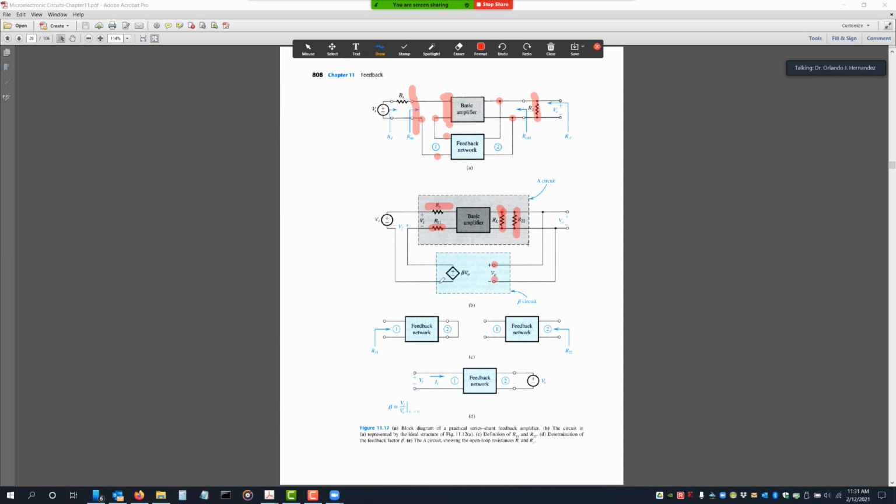So this voltage output over here becomes beta times this voltage over here, VO. And this can be applied to an actual simple negative gain op-amp type of amplifier with the two resistors giving you the gain or the beta.